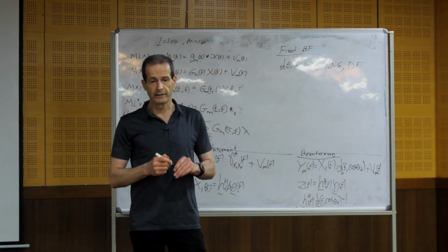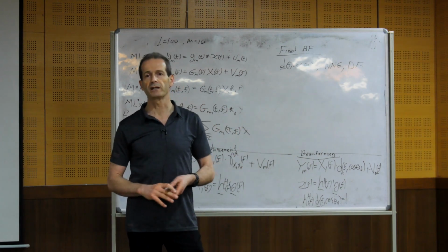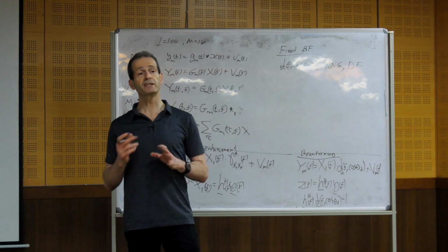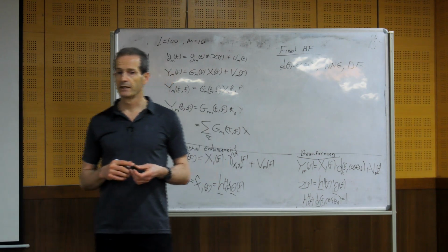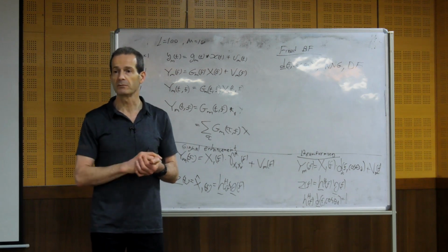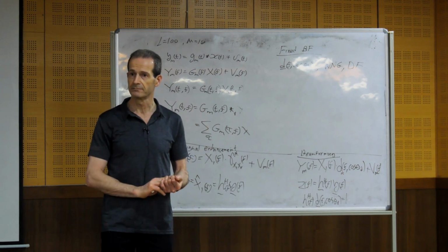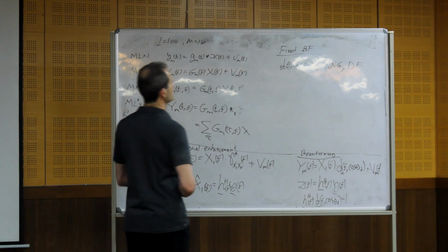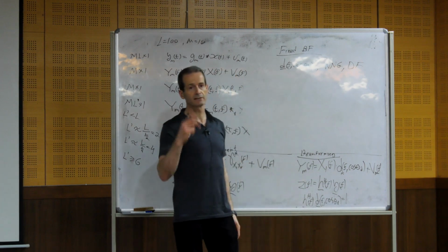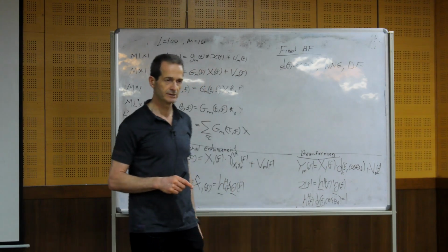I don't know what will happen in a practical environment because I design it offline, outside the environment. I don't make assumptions about the environment. So with fixed beamforming, the advantage is that it will perform equally for different environments because you don't make assumptions about the environment. It doesn't adapt to the environment. But still, I need to assume that I know the direction of the desired source because I steer the beamformer towards a certain direction.